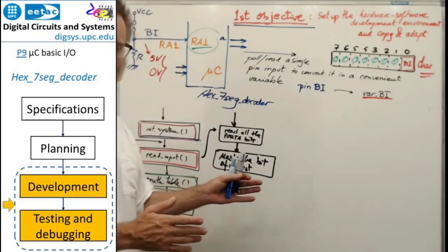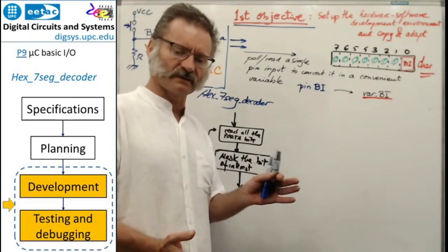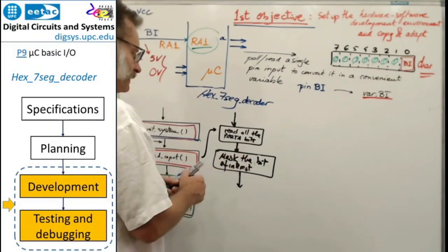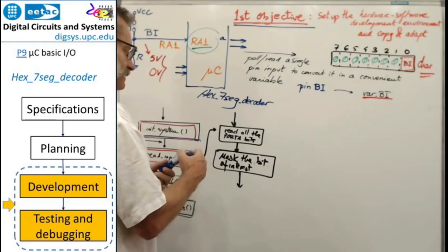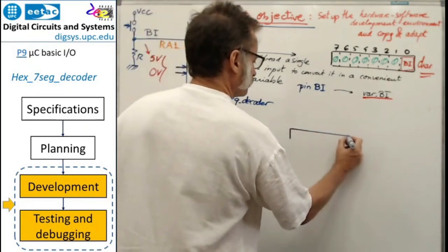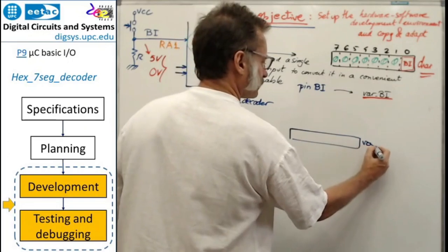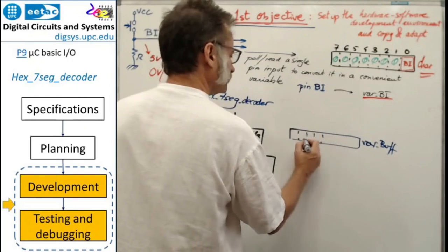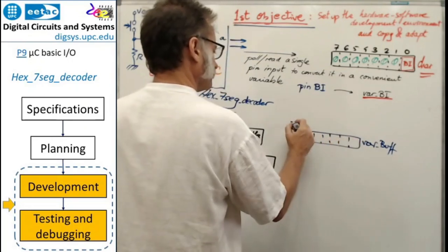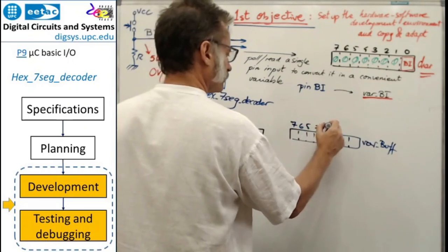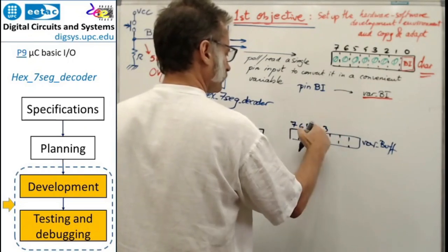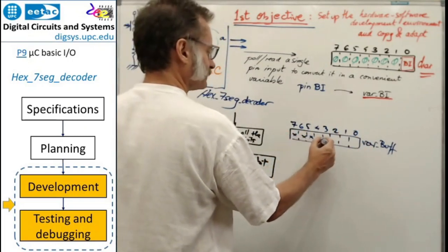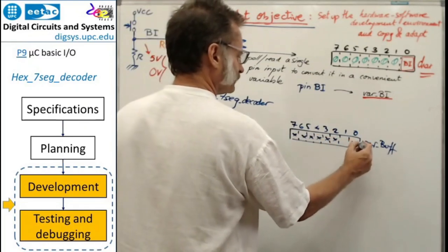And then it's going to be the time to go back to the software hardware environment and put these ideas into practice. So read all the port A bits. This means that in some way now you will have a convenient bar buffer that has 8 bits: 7, 6, 5, 4, 3, 2, 1 and 0, and you are not interested in anything except this bit 1.